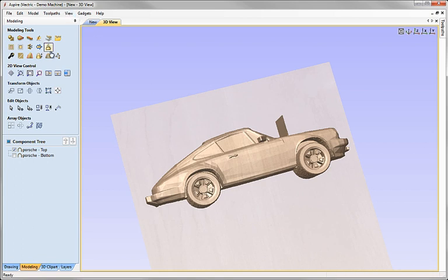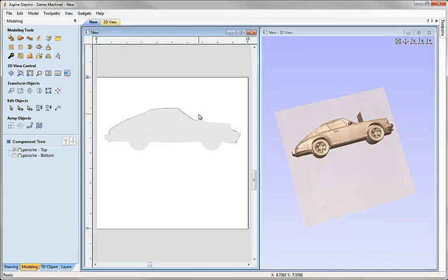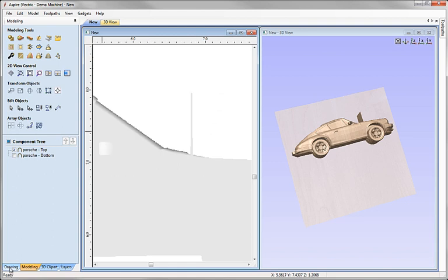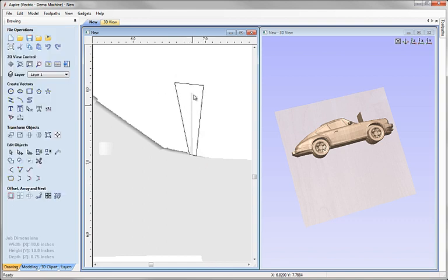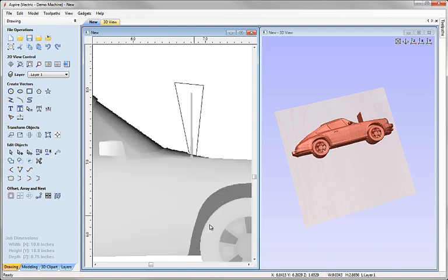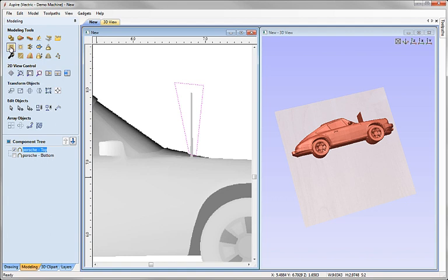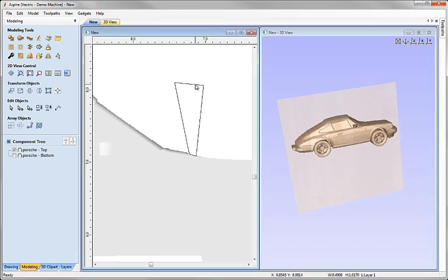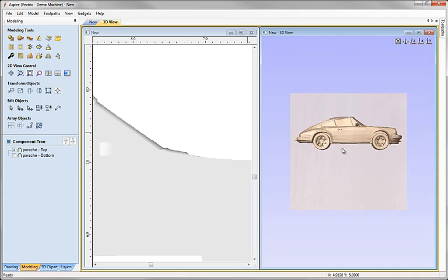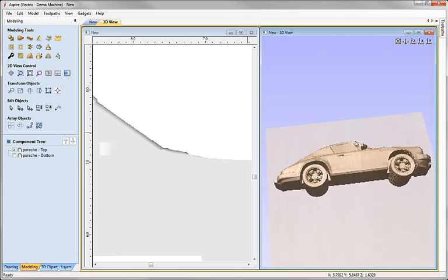So if we wanted to, we could tile the windows, I could zoom in here, and come down to the drawing tab and just sketch a line in here in order to put a bounding box around that aerial. Then we could select the component, shift and select the box, come back to the modeling tab, click on the option to crop that area from inside the box. You can see we've actually edited the model itself. We could even go in there now if we want and use the smoothing and sculpting tools on this in order to try and smooth out some of the facets we've got.